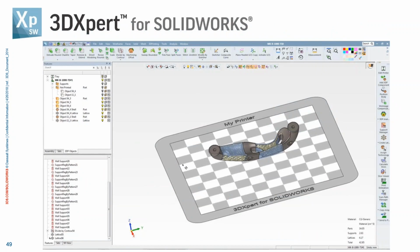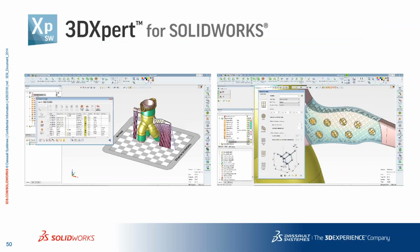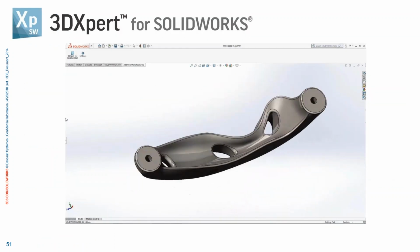So it's a standalone application, but I'll show you how it works. There are some images of how to create the support. And also the structure. Do we have a solid structure? Maybe we want to speed things up or make it lighter to save material. So there are lattice settings, a lot of settings for how you can modify the mesh internally to make it better for 3D printing. Let's see how it works.